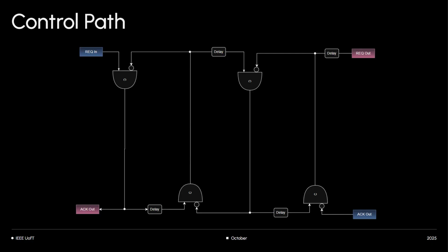Now if you trigger another request, what will happen? It'll travel through, but it won't cross the second last stage, and then after that, it'll get blocked. It'll consecutively get blocked. So first your request went all the way through the 4 stages. The second request went till here. It didn't go through the last stage. The next request will stop here. And then finally it'll just stop here. And after that, no matter how much you toggle your request, nothing's gonna happen.